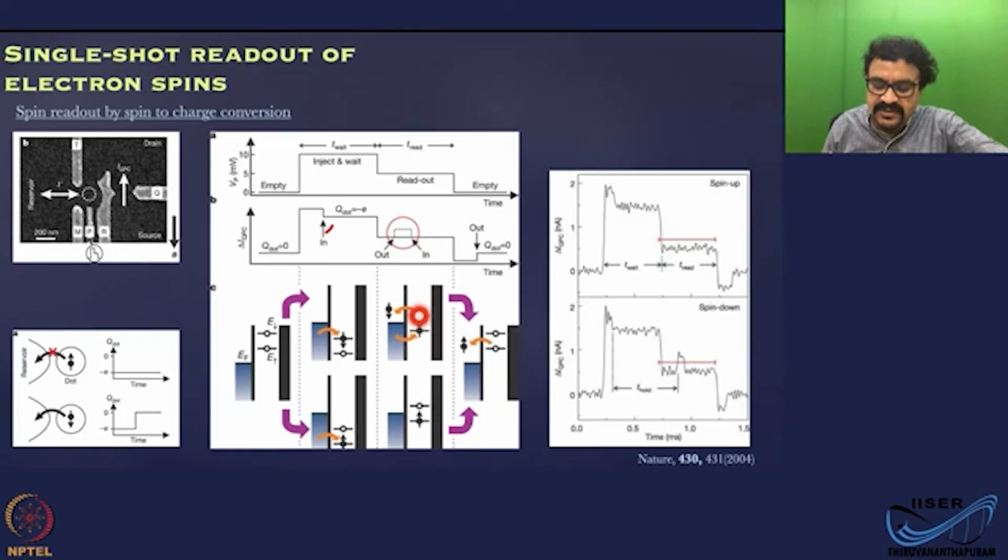But now immediately, since this electron was here, it has tunneled out. Now this state is below the Fermi level, this state can get occupied. That is going to again bring the current back to the original. So the electron tunneling from the upper level will have the point contact current go up, but another electron tunneling back into the lower level will bring the current down. So that is what this thing is. You have here electron tunnels out, then another electron tunnels in. That's what it is.